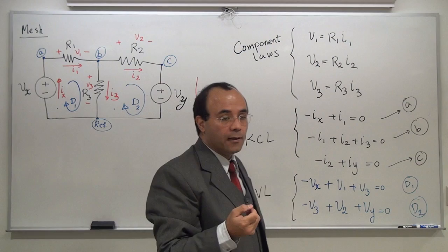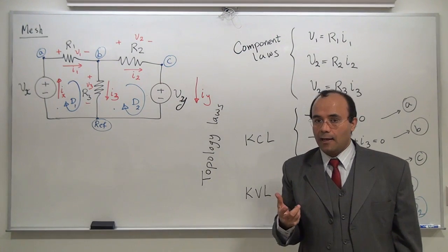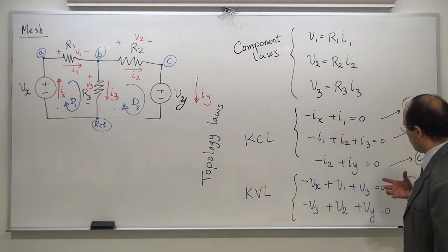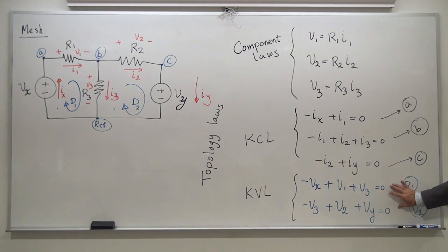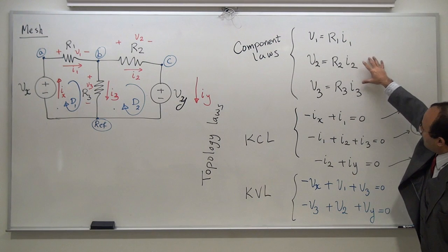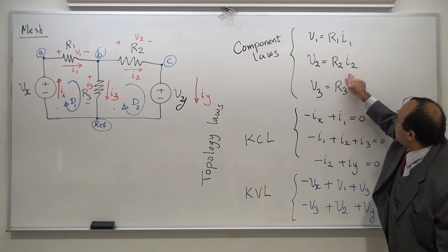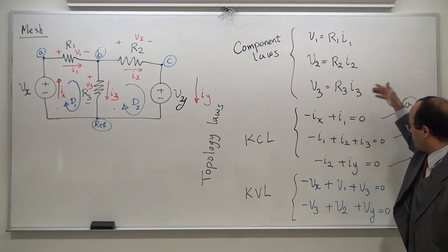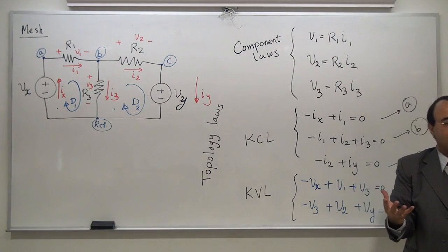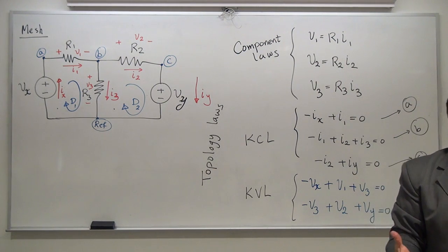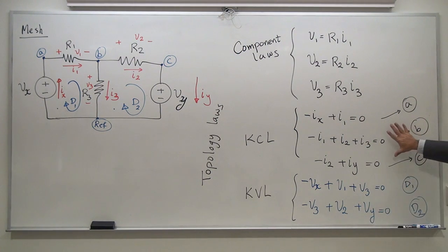What did we do in the nodal approach? In the nodal approach, we said that through a transformation of the component voltage versus the node voltage, you would take care of the KVL law. We took care of this and inserted all that. We found I1, V1, R1, I2, V2, R2, I3, V3, R3. We put them in and came to the conclusion that an 8 by 8 system can be simplified on the basis of the KCL law.